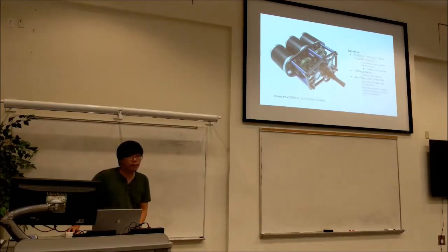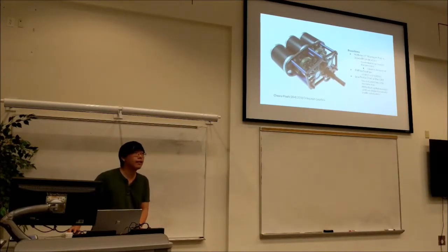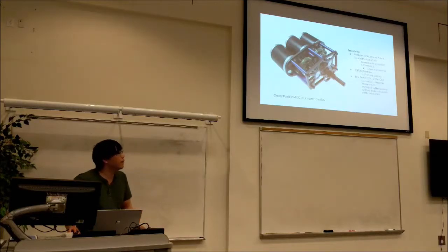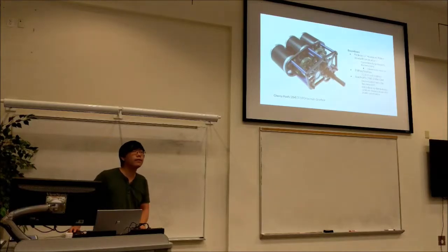And then also, it's important to consider why they designed this. It's a unique design because it's much flatter than most 3-CIM gearboxes. In this case, they use Mini CIMs, but it's the same thing. The way they achieve that is, if you'll notice the Mini CIM here, the pinion is connected to the first stage of the other 2 motors.